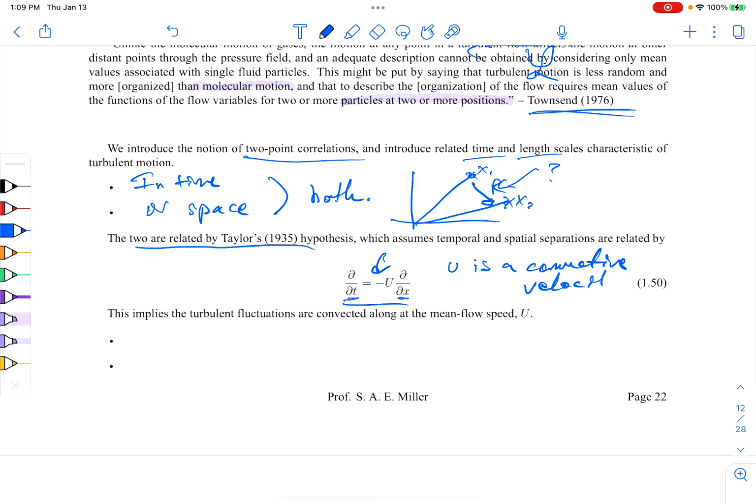And that's the speed at which turbulence moves through space. And unfortunately, it is an approximation, because measurements show that the convective velocity of turbulence sometimes is not equal to the average velocity of the flow. For example, this tripped me up and almost lost me my Ph.D. dissertation. I'm an experimentalist, and I made this approximation that the turbulent structures are moving at the mean flow speed.